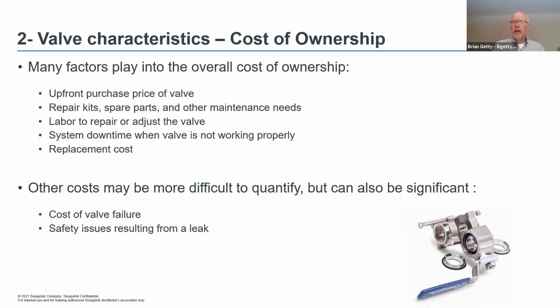Is this valve installed in your plant, or is it installed an hour and a half by helicopter to an exterior site, a site further down the line, where you have to go in and do some repair work? At that point, the initial cost of the valve is no longer an important factor. You want to keep your cost of maintenance down.